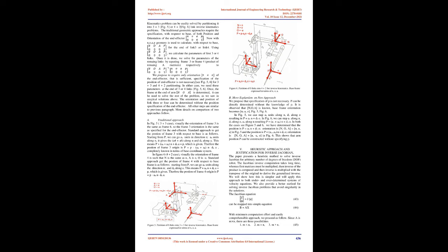Let the position P be provided for this example. Geometric approach to inverse kinematics. Here we provide an efficient way to solve inverse kinematics and the inverse Jacobian problem. We determine the intermediate frame at the end of arm, link 3 or link 4, between the base frame and the end effector of a 6-link robot. It makes it easy to solve the 3-link or 4-link inverse kinematic problem.